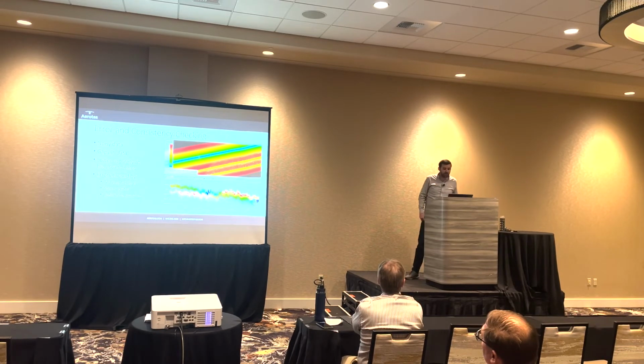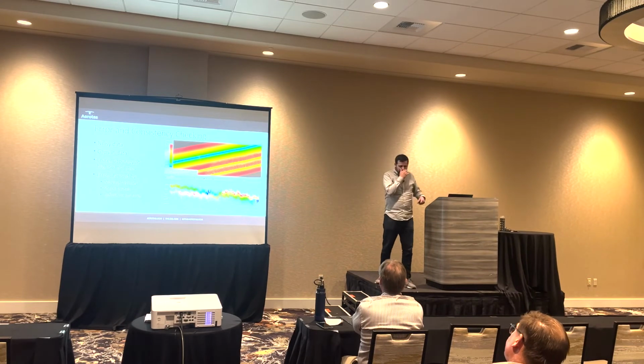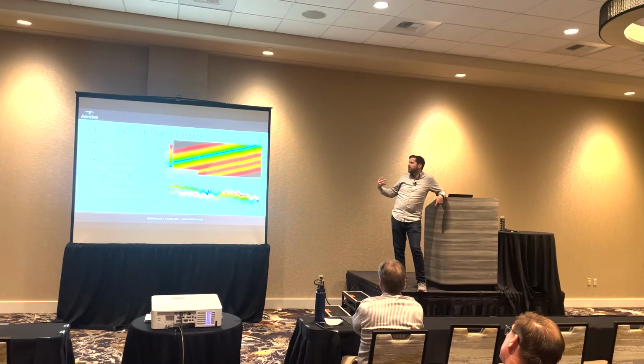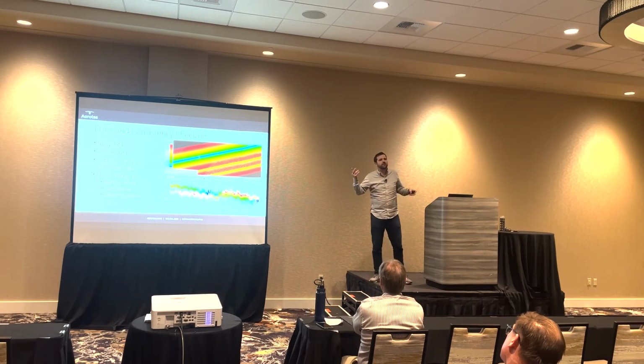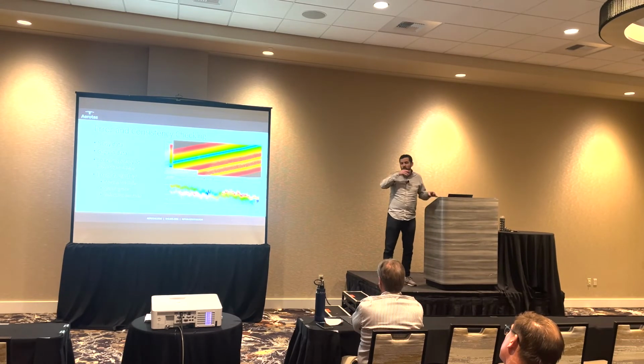It's part of why we like having a little bit higher overlap, which we talked about yesterday. That higher overlap means that when you see something like this, you can say, oh, we've got high scan angle deviation, and you can just cut out anything with a scan angle above 30 degrees, for example, and that'll get you much more reliable data. Because the L1, like I said, is not the most accurate LiDAR system in the world. It occasionally has issues like this.